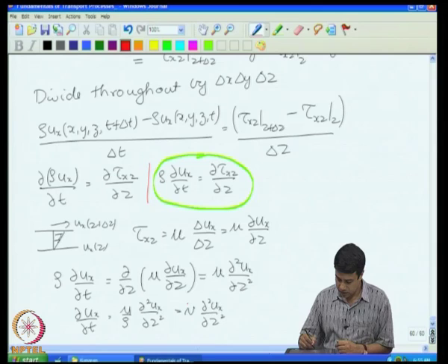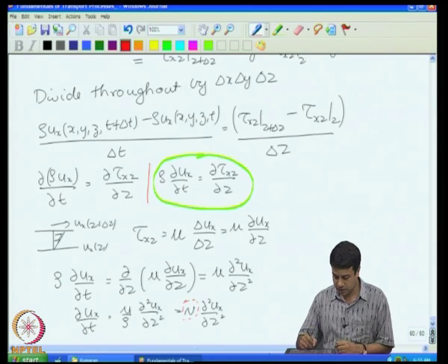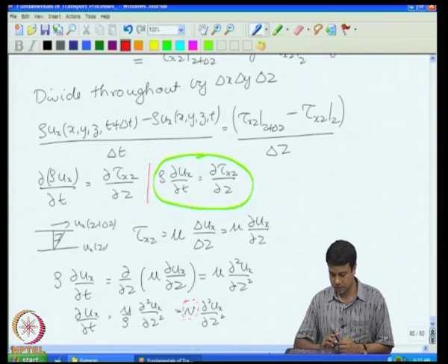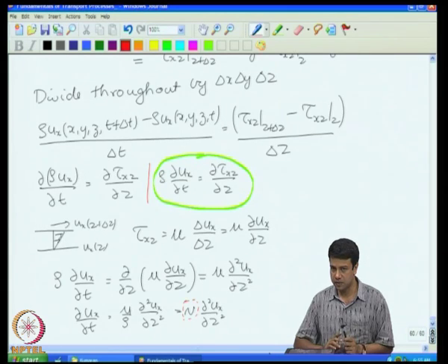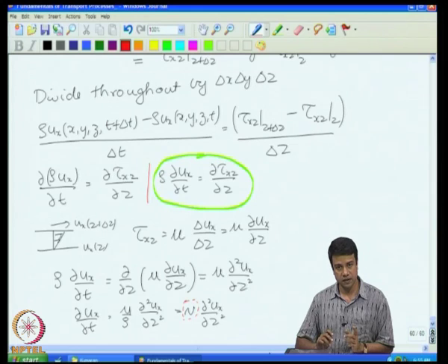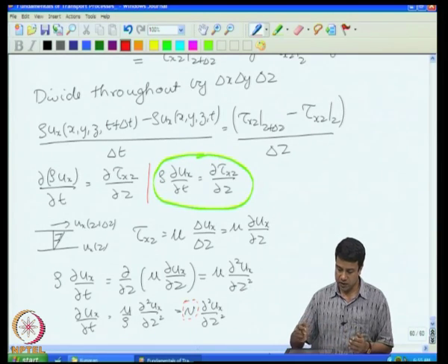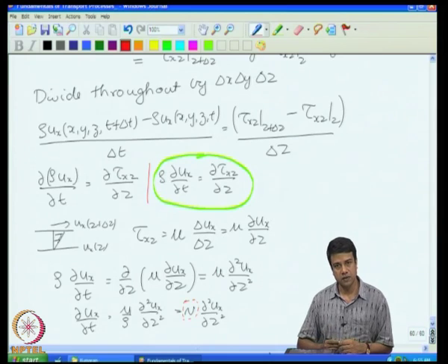And this kinematic viscosity is the momentum diffusivity for this particular problem. We used a slightly different methodology for momentum transfer as compared to heat and mass transfer. The reason was that for heat and mass transfer, the flux into a differential volume is considered positive, and therefore we got equations of the form dC/dt is equal to minus dJz/dz, whereas in this case we had defined the stress to be positive if it is defined with respect to the outward unit normal. So, we do not have the negative sign in the constitutive relation. However, when we put that into the balance equation, we still get an equation of the same form.